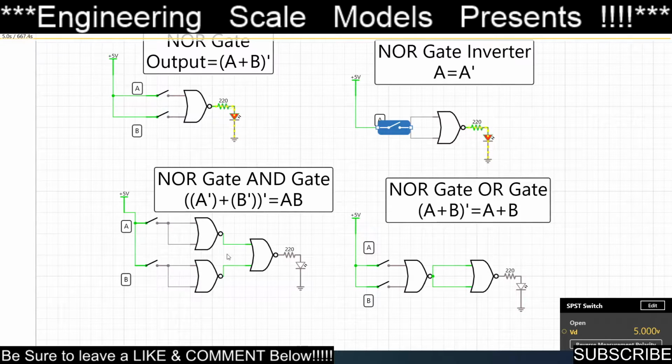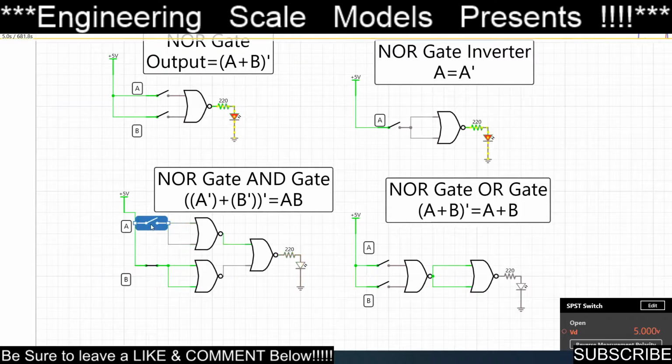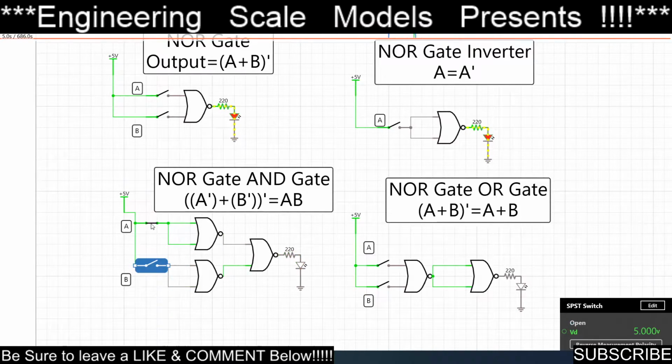As you can see here, if I turn one on, the LED is not on. If I turn another one on, the LED is on. So AND is, when they're both on, it's on, but when only one is on, it is off. So that is your AND gate. And if you wanted a NAND gate, you could slap an inverter in the front of it.